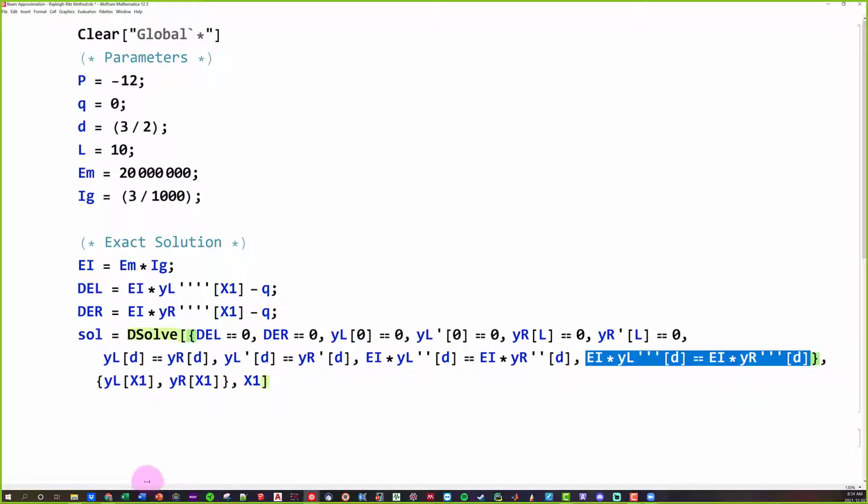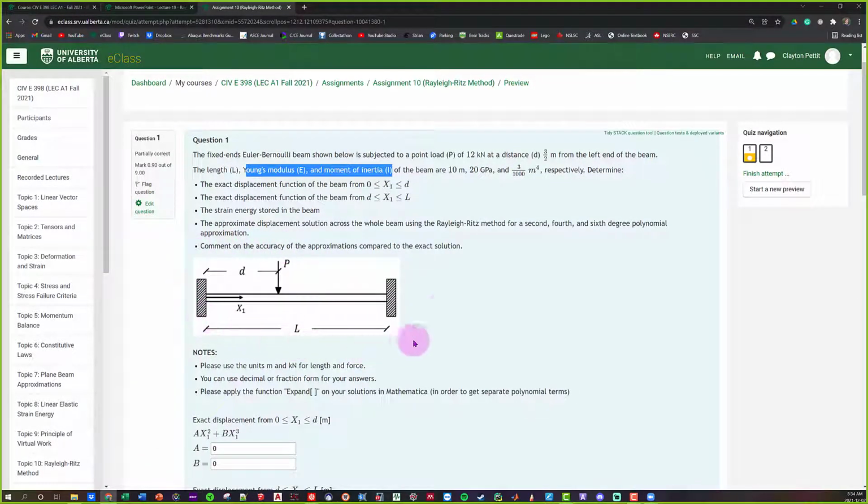No. And the very simplest way of picturing that is we know if we were to draw a shear diagram, there'd be kind of a constant shear here because there's nothing going on. But when we have a point load, we know that there is a sudden drop, either upwards or downwards. In this case, it's going to be downwards. So the shear on both sides is going to be different, and the magnitude of the difference is going to be equal to P. So let's answer this question because I think this will help the best. Which side, left or right, will the shear be higher? Which side will have a higher shear, the left or the right side?